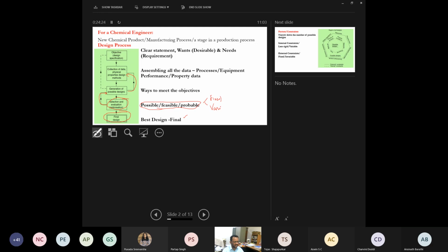Then, applying the efficiency of the column or tray, you can get the total number of stages required. And this efficiency is the average efficiency; normally it will change from tray to tray. Okay, because your feed is located somewhere between the stripping section and the enriching section.